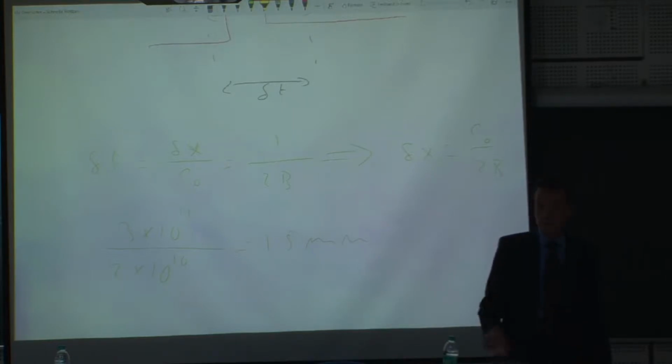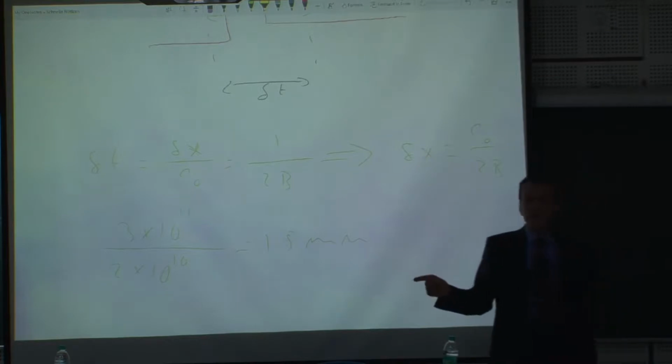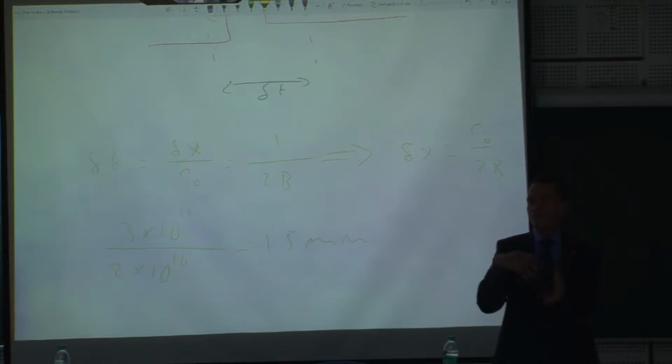But otherwise, the bandwidth you can deal with, with the fastest processors, is something like a maximum of 2 giga. I don't think that you see something much larger than 2 giga. But this is not the only problem, because this is only the digital signal processing. Much worse is, if I'm really measuring in free space, I have antennas, because I produce the plane wave by a generator, and this antenna has a bandwidth.